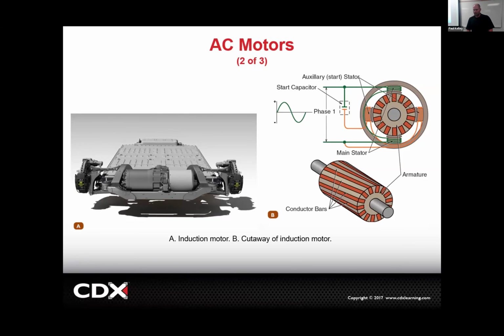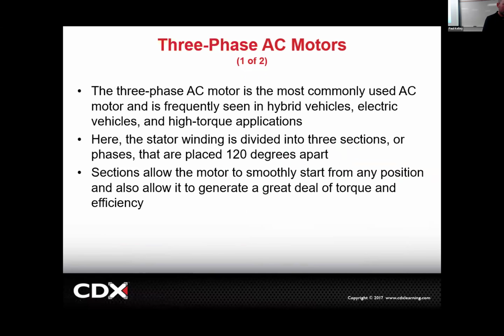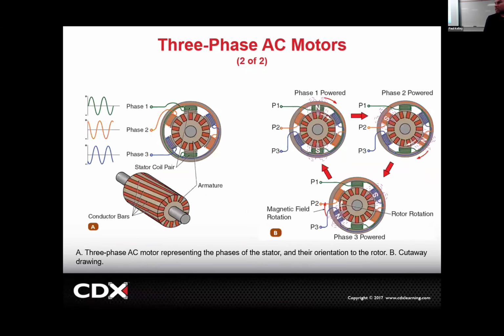But if you take a hybrid or EV class, we'll definitely do that, because we need to verify that these are correct. Additionally, the AC motors generally are going to be much higher voltage, so we need to test these phases and make sure phase 1 is not shorted to phase 2, or phase 2 is not shorted to phase 3, or phase 1 is not shorted to phase 3. So there's a bit of a different way of testing an AC motor. It's not just measure 12 volts and ground. It's a little more complex.